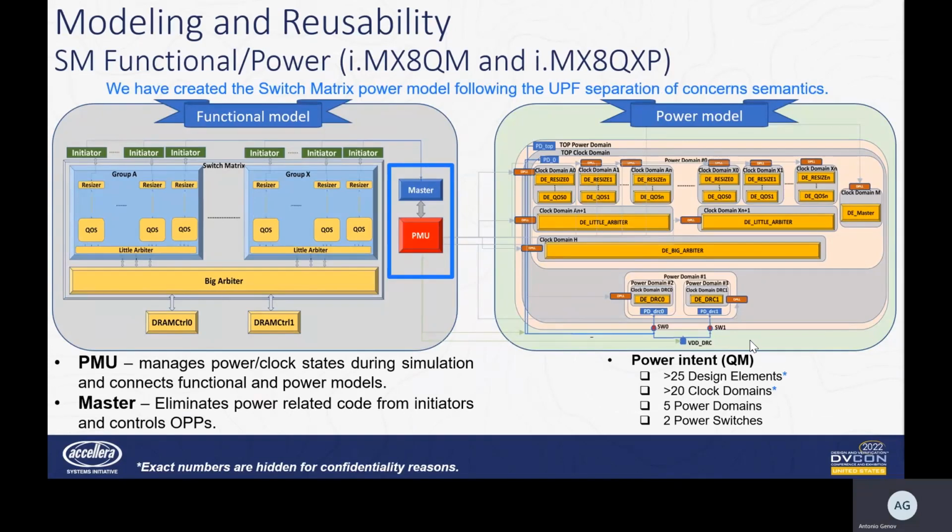Since the power model and the functional model are separated following the semantics of UPF, the functional model must also contain the configurable PMU module provided with power clock arc, which contains the power and clock state table, manages the power and clock changes during the simulation, and most importantly for us, it makes the connection between the power and behavioral models.